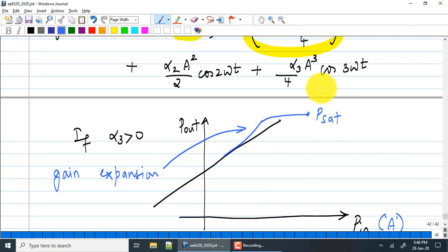In either case, in the compression case it would do this. In fact, in the compression case, it may do this. Because Psat fundamentally will just be limited by the supply rails, the maximum swing you can get. I think we discussed this very briefly last class. What you can extract out of an amplifier will in the end be limited by power supply and ground, come what may.